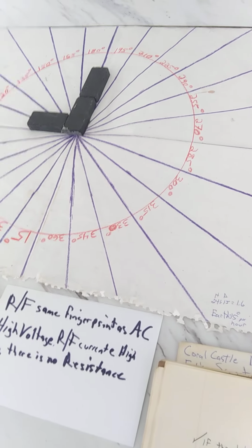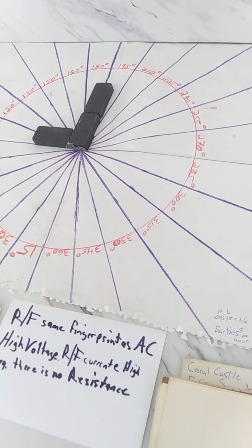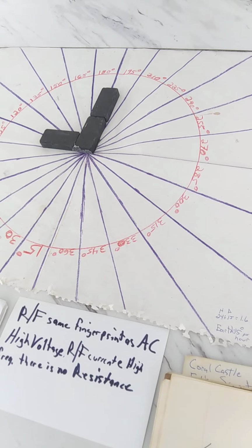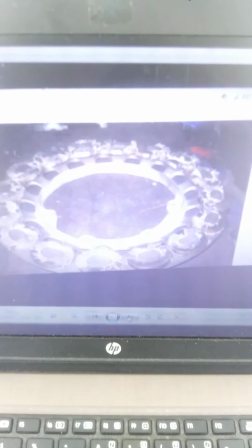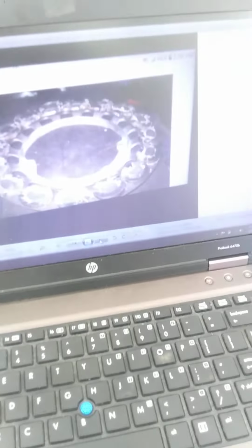Okay, so all those are tying up to that magneto post. The faster the flywheel spins, the higher the current produced. So that's how this thing's working so far here. Here's a picture of what that coil ring looks like. 16 copper wound coils, and they're all strung together.